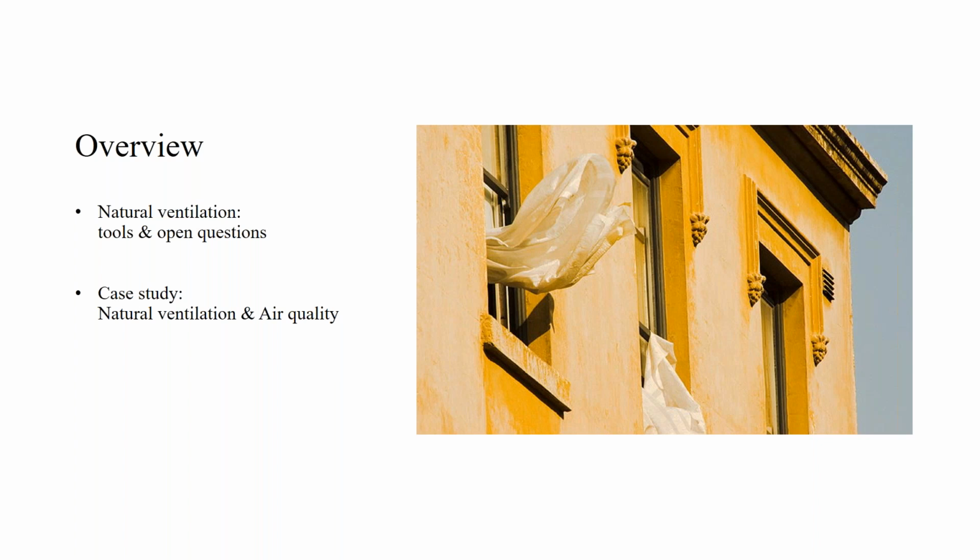And again, there is a lot of input by the user when we deal with natural ventilation. So there is a lot of uncertainty given the various parameters that are chosen on the CFD side, from turbulence models or convergence criteria to mesh type. So that was more a past experience.